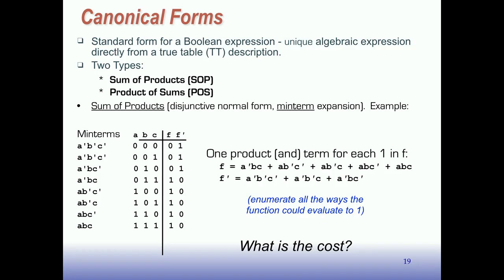So if we know that, and just forget about the inversions for a second, because we can take the 3 inputs and make inverted versions of them. So worst case, we're going to add 3 inverters to the whole thing. But just looking at the AND and OR gates, if this is a 3-input AND gate, we can say roughly it's going to cost 6 transistors, right? And we have 6 times whatever that 1, 2, 3, 4, 5 here.